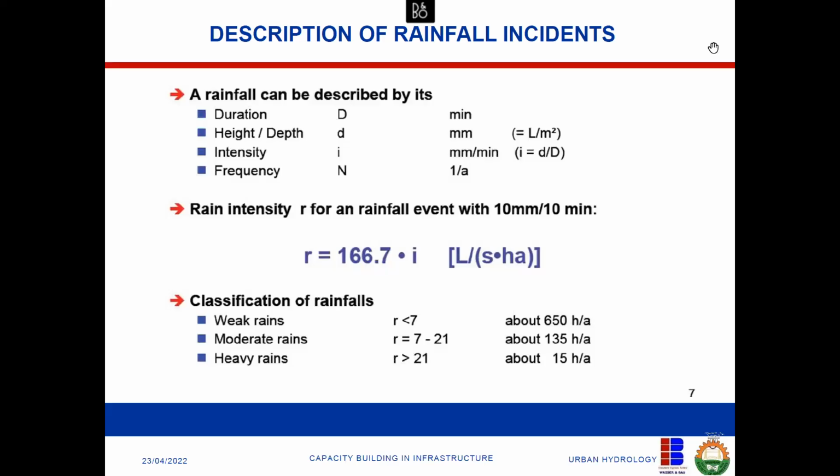These parameters of rainfall frequency are a determinant factor to know how your design will go, whether you're using 5 years, 10 years, but there's a table that will make a recommendation based on your design concepts as an engineer. If you want to design for storm water, it's good that you ask your clients, how long do you want this thing to last? And you need to ask yourself, am I designing for normal drainage or am I designing against flooding? Am I designing against surcharge? That's what we call it. Surcharge, normal surcharge. Water is rainfall, the water is surcharging, and you need to control it with your drain.